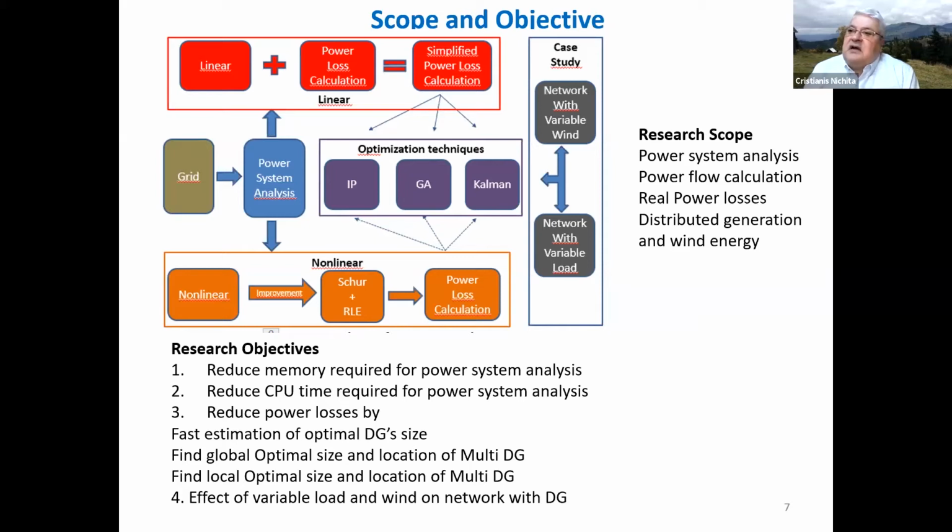Since the fast predicted linear model causes error in estimating the optimal DG size, we must extend the methodology to analyze multi-DG units based on, for example, wind energy resources, as well as finding the optimal placement of each DG as a part of the future or actual network.